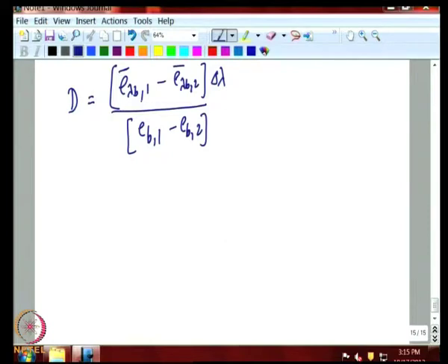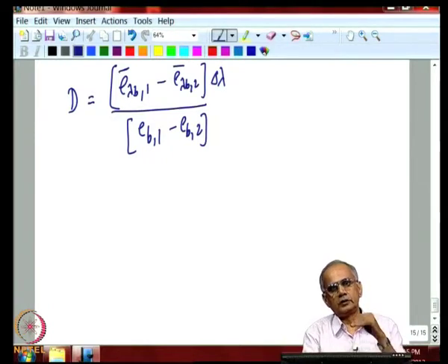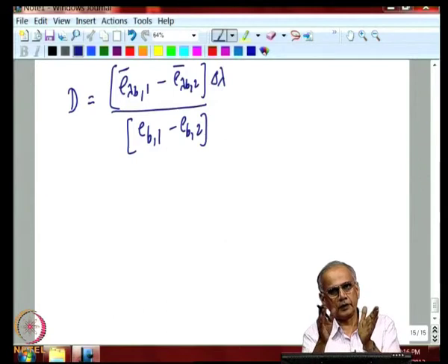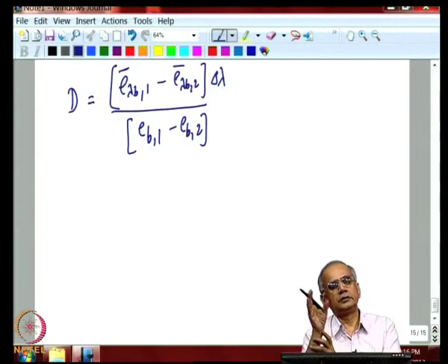So this can be thought of as the amount of radiation exchange in the absence of a gas between surface 1 and surface 2 in this wavelength interval delta lambda, compared to the radiation that is transferred from 1 to 2 at all wavelengths. So, this is crudely a measure of the radiation lying in the lambda range compared to the total.